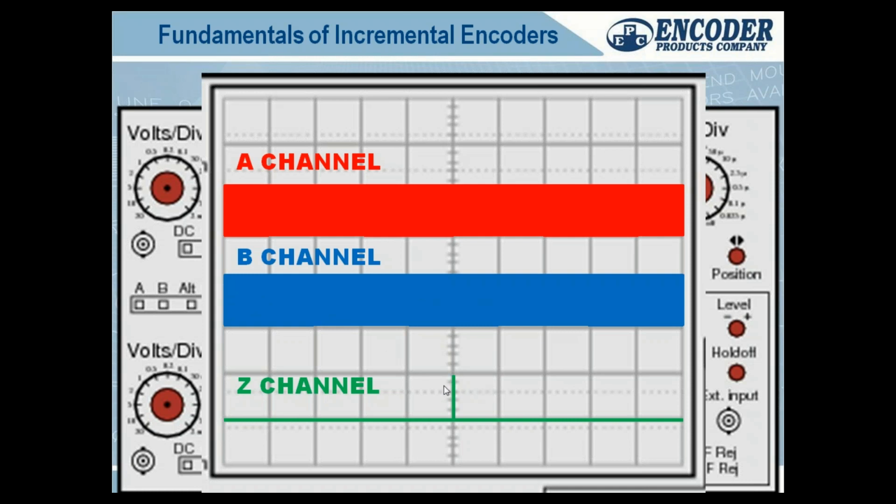So if we start counting to 1,100 and then we see the Z, that VFD is going to trip with a PG alarm, a pulse generator alarm, or an encoder alarm, feedback alarm. And that's because it's going to go, we got a problem. This encoder is not putting out 1,000 pulses per revolution. It's not working. So the Z pulse, even though it often gets thought of as a home, and that's what it's often called, it's also a great tool for error checking.